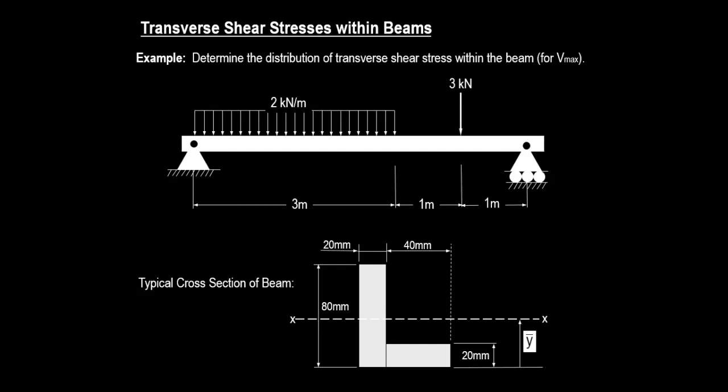Natasha is going to tell us what is the first step. To find the reactions? Yes? Okay. Good answer. Not only the reactions, the next step is to find the shear force diagram. Why do we do the shear force diagram? Because in one snapshot, it shows you the maximum number. I can't imagine any other way of telling you what the maximum shear force is.